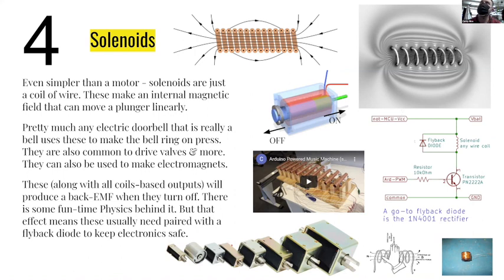But if you're worried about it, you can apply a diode like this, which gives the solenoid a safe place to dump that current back. This is totally a good move to have in here. And then transistors like this, I think we tried to order a few of those. So there should be some transistors, which are electronically controlled switches. Another output that's interesting in its own right. And so with these, your Arduino can control whether the solenoid is on or off.